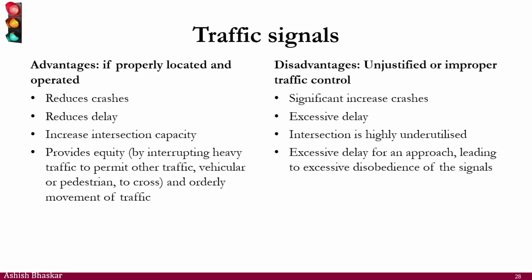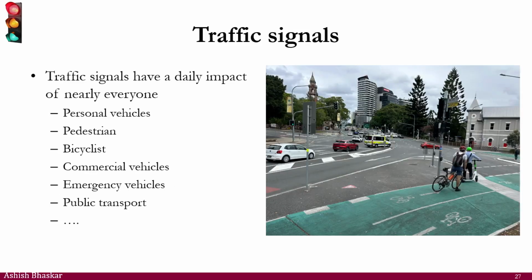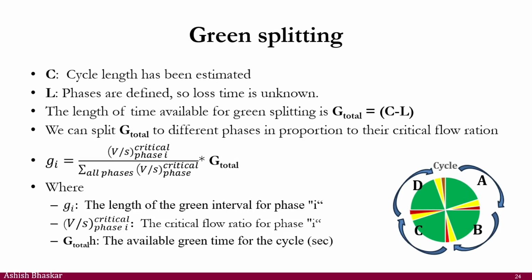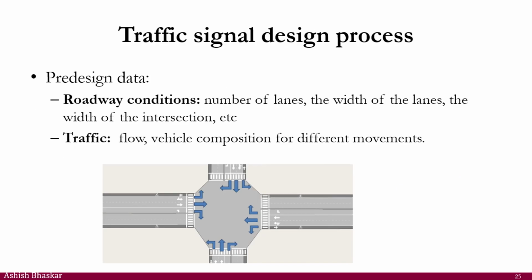At an isolated intersection, if you're only looking at one intersection, it doesn't matter much. But if you're looking at a group of intersections, it will matter a lot, the way you coordinate one with another. So the order of the phases, for only one intersection, you're not worrying about the other ones, based on the way the demand is approaching. This is a very complex thing. The way the demand approaches here depends on the way the upstream intersection is defined. So if you try to coordinate these two, so that when the traffic is approaching here, that's the time I should be giving green to this one, then obviously the order matters and will make a big change.